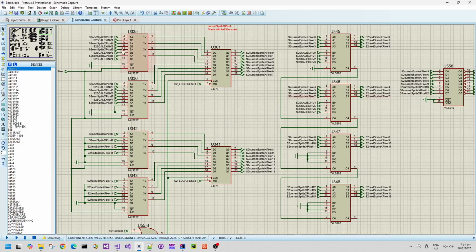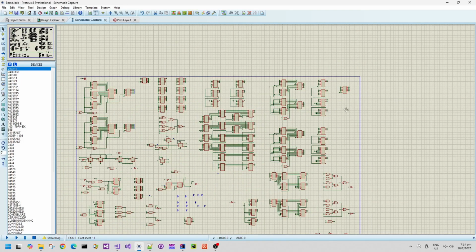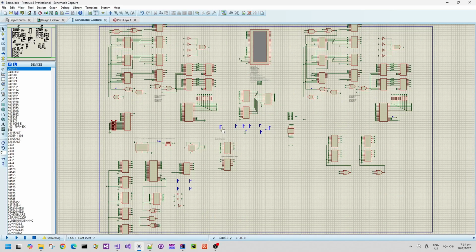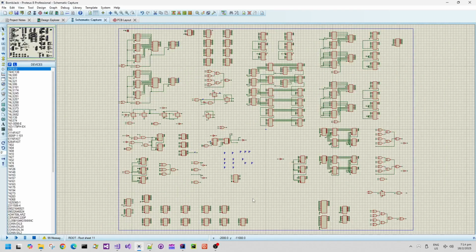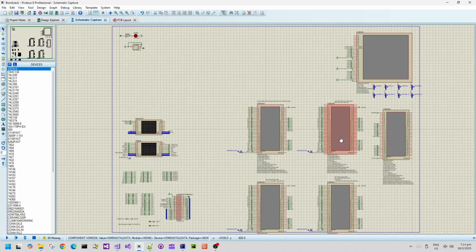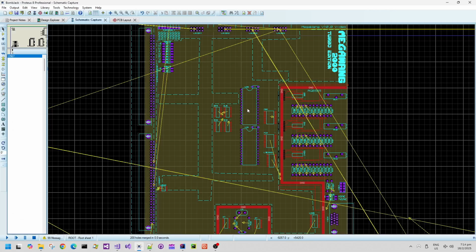So internally, it is a 16-bit value which gets accumulated progressively with 8-bit values. So there's an unsigned addition going on. All of the adders and everything like that are 2's complement binary based adders as well. So the 2's complement mathematics for binary arithmetic tends to work out quite well. So I'm really happy with that test of the simulation.